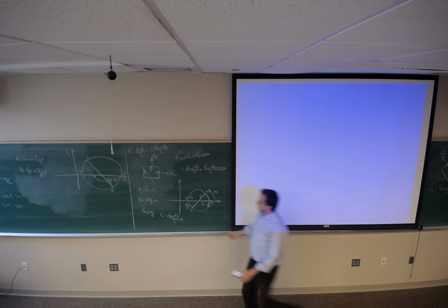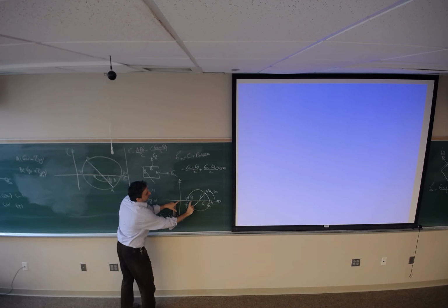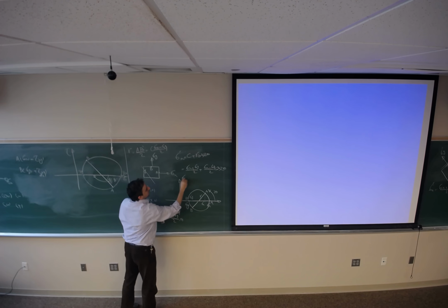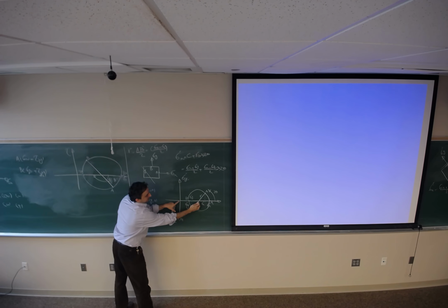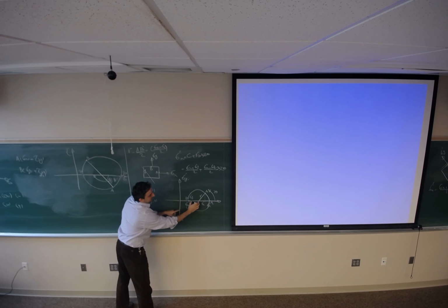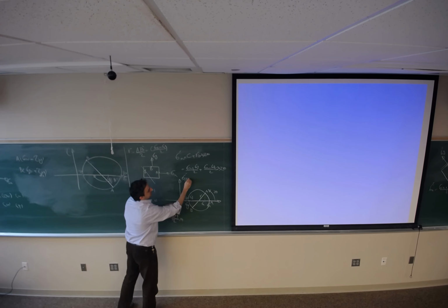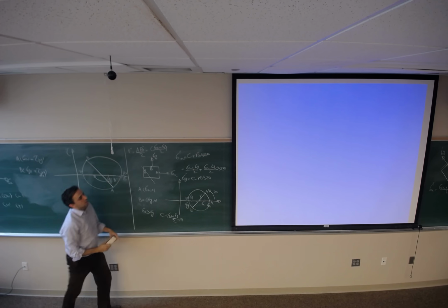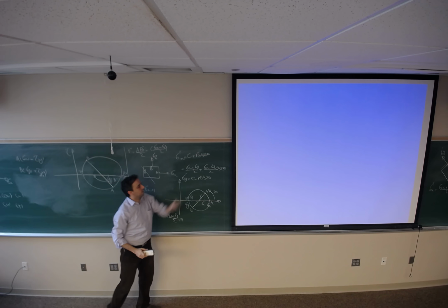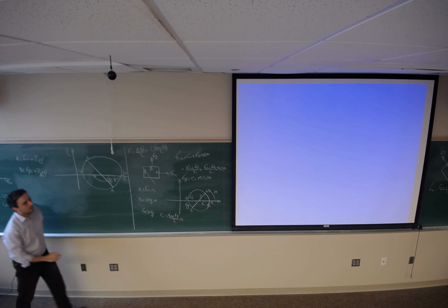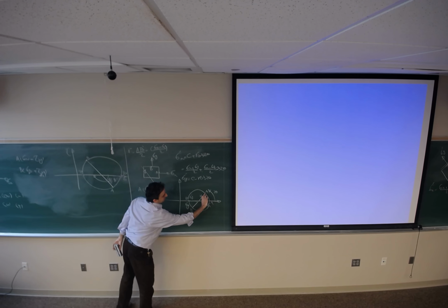Same thing for sigma prime y. Sigma prime y is going to be the center minus this distance, center minus r cosine of 2 theta. Just change this positive to negative, and you will get sigma prime y. And what is the tau xy?